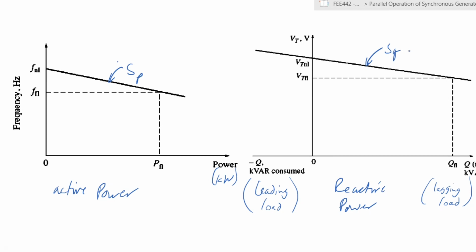So you see, for example, what we have mentioned before, the droop of speed, right? The generator at a certain power FL, let's say the full load power, will be at a frequency that is given by that. As you go decreasing the amount of power that the generator is supplying, the frequency of course will increase, naturally, because of the characteristics of the governor. So the governor keeps that relationship in a linear form.